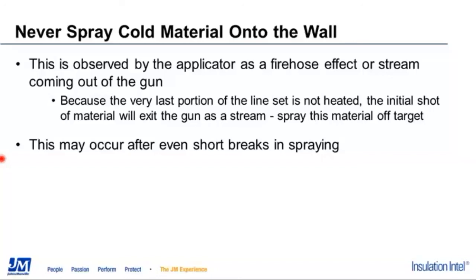And let's make sure that we know that we're making good foam, good atomization, good cell structure before we take that material and go from that off-target spray and start putting product in somebody's walls. And then during the wintertime, if you take a 3 or 5 minute break, you could end up not being able to spray without going off target again. And during the summer, maybe that's 10 or 15 minutes, but have that piece of plastic there.